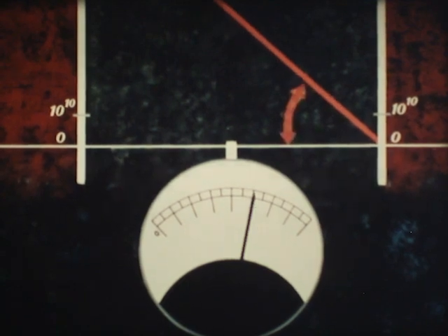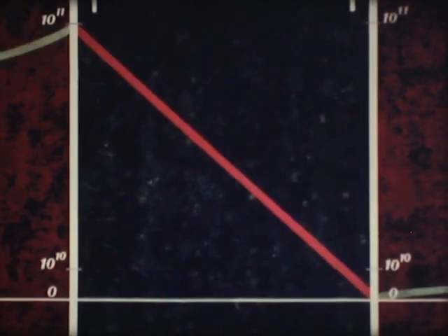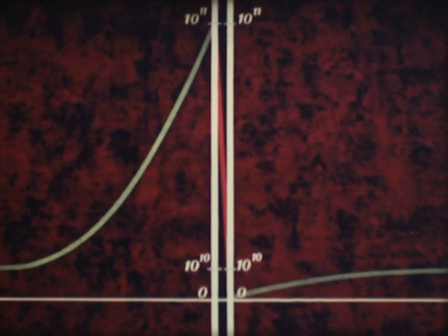The currents flowing in the crystal are also related to the concentrations of the minority electrons in the P regions. Close to the junctions, the concentrations deviate from the equilibrium level, but the small deviation at the right-hand junction can, for the moment, be neglected.